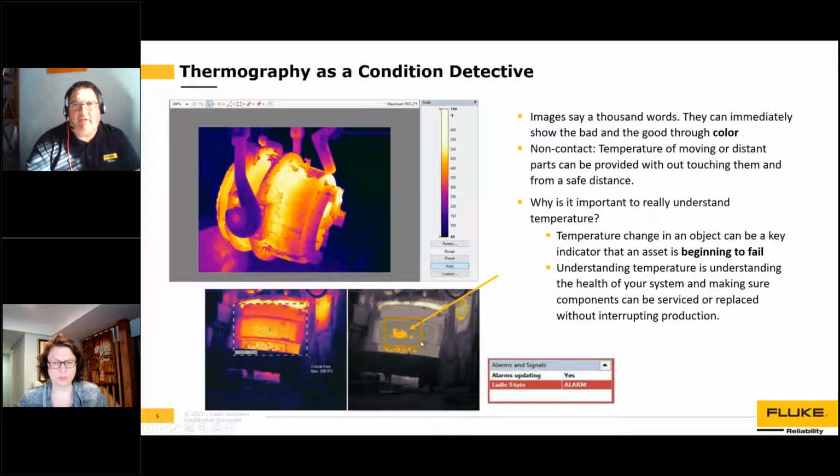In fact, what you'll see here is the black and white showing the hot spot in yellow. So it's extremely evident where that spot is and where you may need to do service on your product. As far as giving a recommendation, it's hard. Every surface is different. What we usually recommend is that when a system is first set up, we take a look at it as it's running through its process, and we filter through the different palettes to present the best color palette for what you're trying to see. There is no one correct answer for all applications.